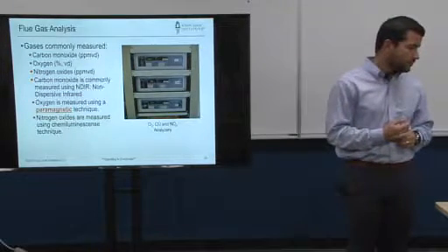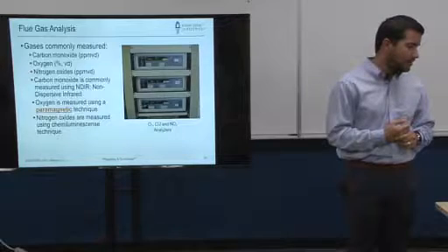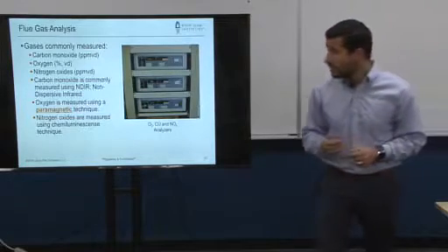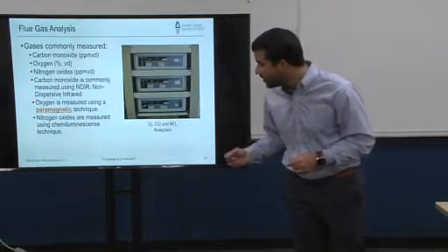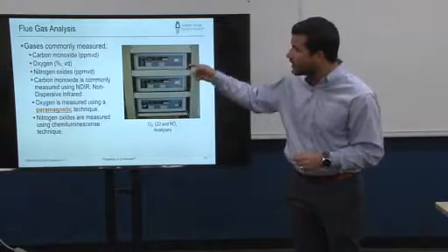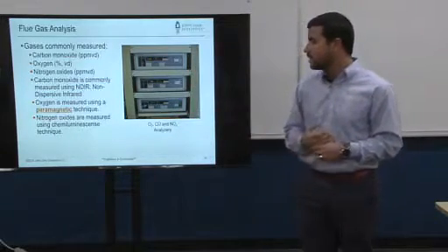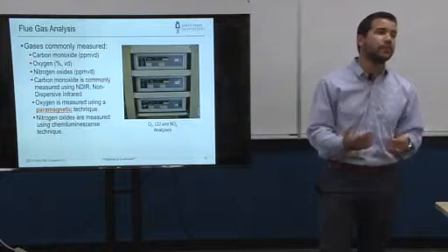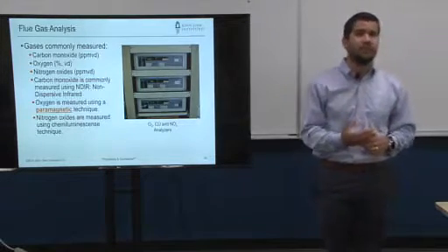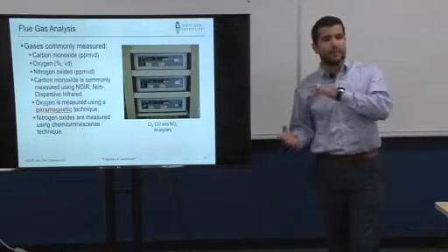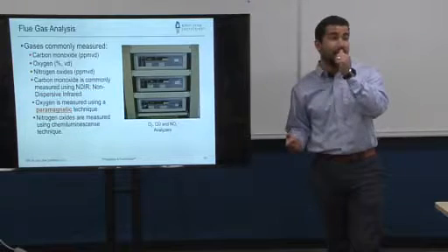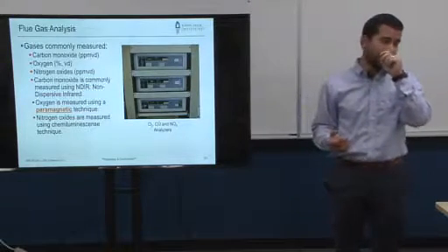So carbon monoxide analyzer, these are actually the 3 analyzers, and I think this will be your NOx analyzer, CO analyzers, and O2 analyzers. They look about the same. They get calibrated every single morning, and they get maintained, I think, every 4 months or something like that. Like, that's literally what we rely on at the test center.